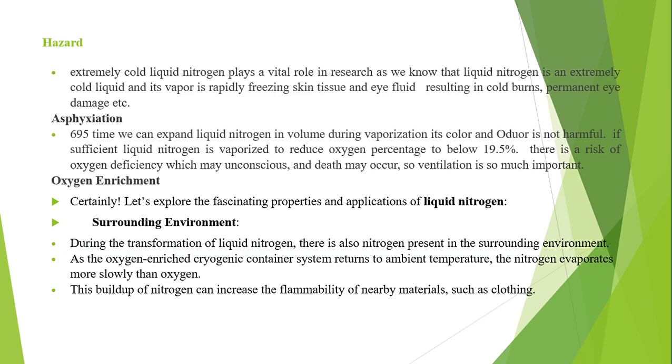Hazards. Extremely cold liquid nitrogen plays a vital role in research, but it is an extremely cold liquid and rapidly freezes skin tissue and eye fluid, resulting in cold burns, permanent eye damage, etc. Asphyxiation: liquid nitrogen expands about 695 times in volume during vaporization. Its color and odor are not harmful. If sufficient liquid nitrogen is vaporized to reduce the oxygen percentage below 19.5%, there is a risk of oxygen deficiency, which may cause unconsciousness and death. So ventilation is very important.